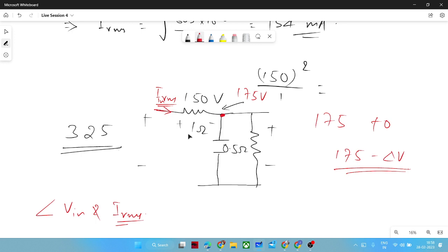Yeah, Vinay, you were saying something? Yes, sir. If we use a resistance method for inrush current protection, we should be using a high value of resistance, right? Again, there is a trade-off. If you use a high value of resistance, your losses and your drop will be higher. However, your protection will be better.